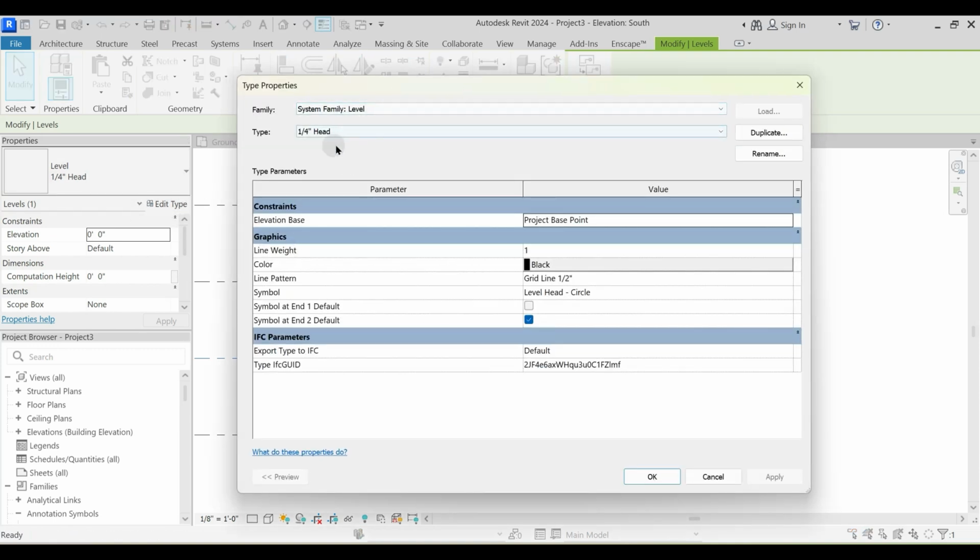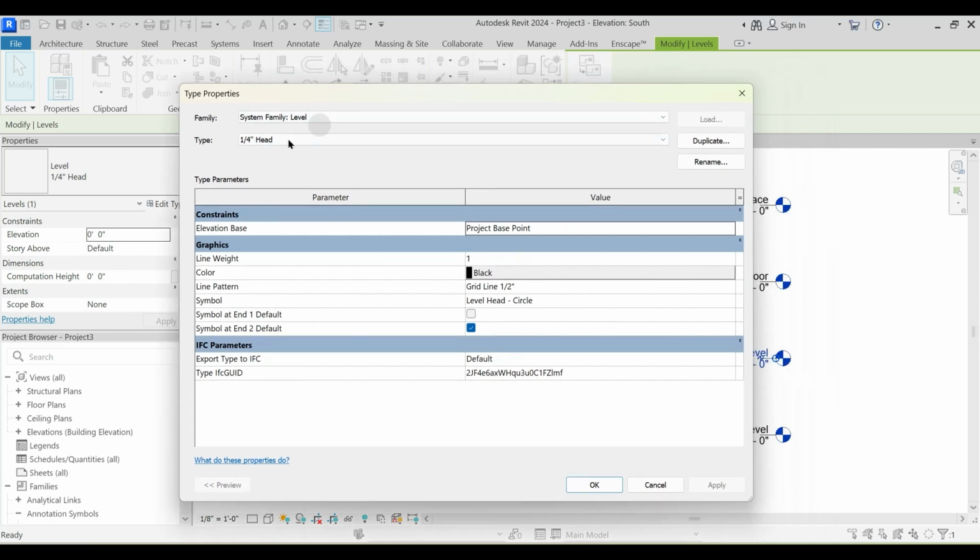And since I said that Revit is a bunch of families, whatever customization you do to a particular family, don't do it to the family that you have selected, but always learn to duplicate, because you might make changes which might or might not fit your expectations.